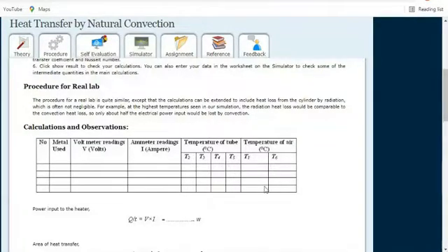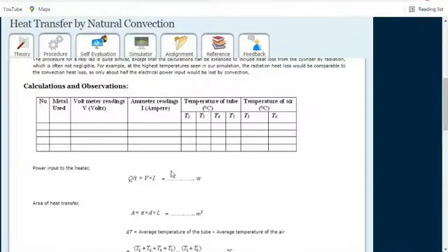Okay, and then the calculations part, we can calculate the value of Q, how much is given by the heater. And obviously as the air flows through the channel between the wooden box and the cylinder, there is definitely an exchange of heat between the surface of the cylinder and the air. And as there is no heat out from the rectangular duct, because it is made of wood, and wood is a good insulator, we can calculate the Q.